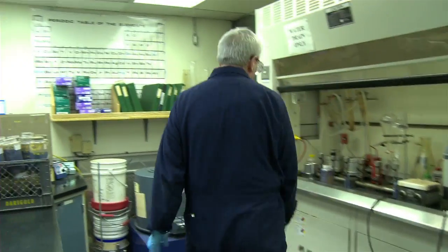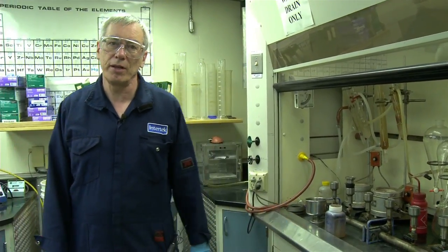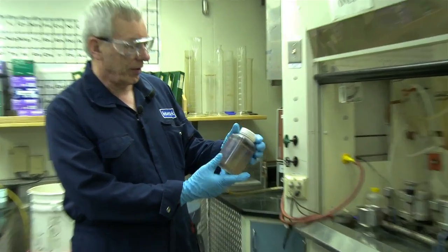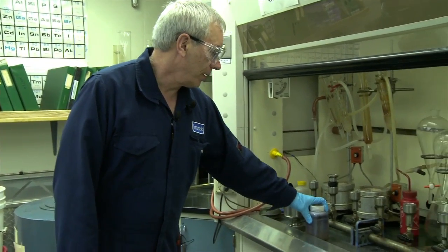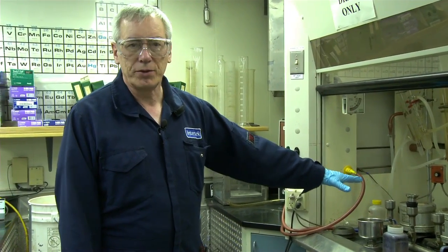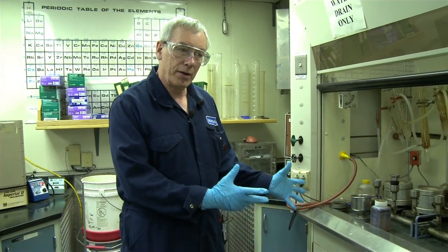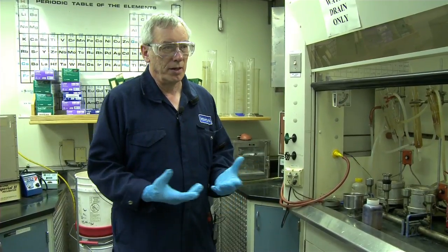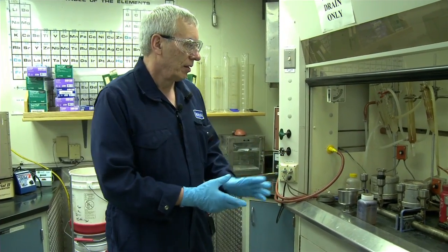Over here is a sample ready for what's called TSS, which is total suspended solids. In a lot of cases this is mostly produced water. We'll go through a manifold with a filter, and the object is to find out how much suspended solids are in produced water. There's a lot of rock flour occurring over at GC2, and they're interested in knowing things like that,